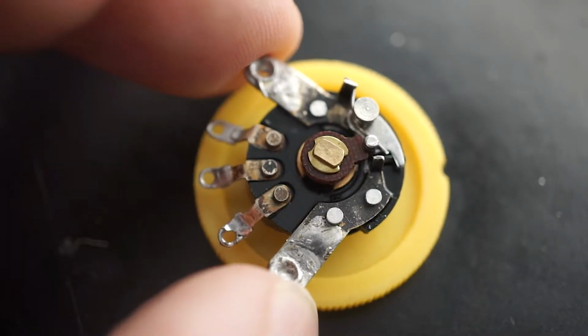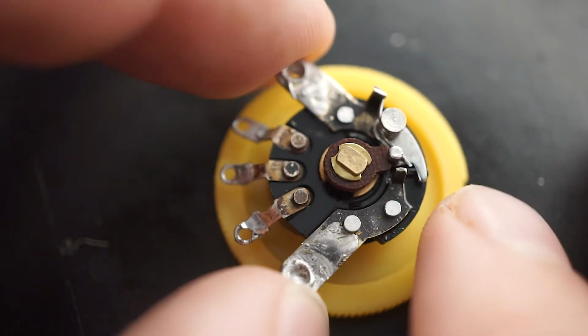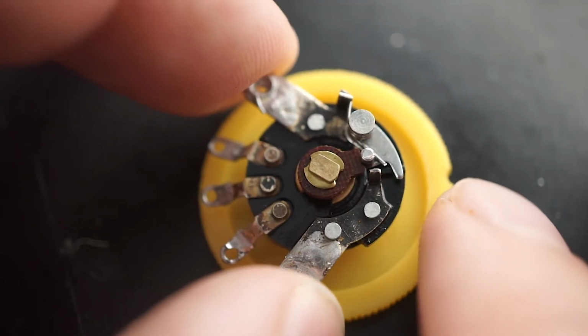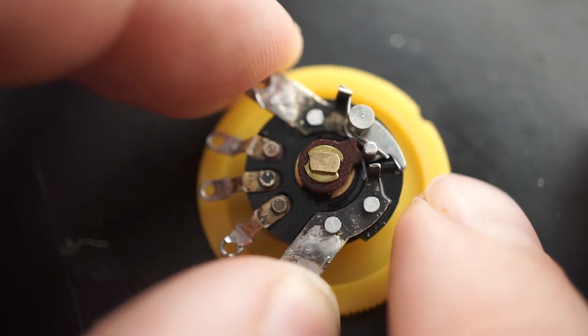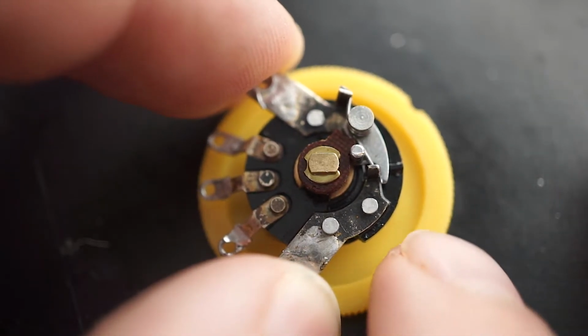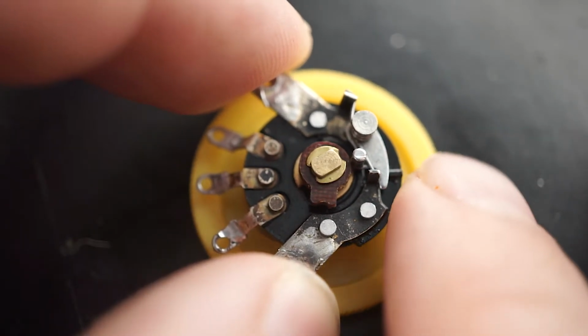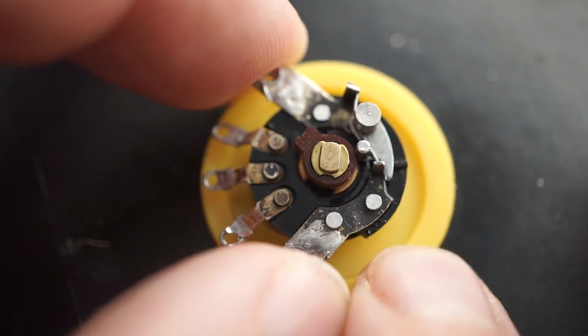I really like these mechanical solutions for both turning the radio on and controlling the volume. You can see that as the wheel turns, the switches drop to connect the 2 outer leads. The 3 leads between my fingers are the leads to a potentiometer, which I'll use to control the volume.